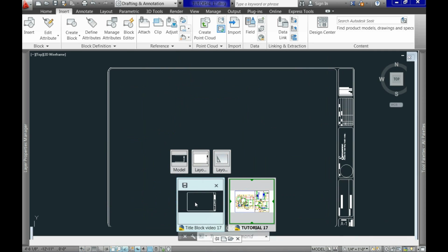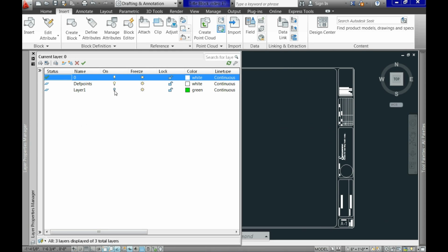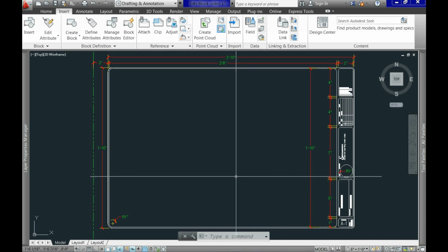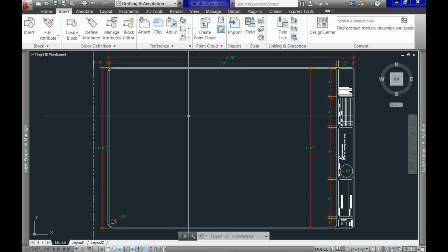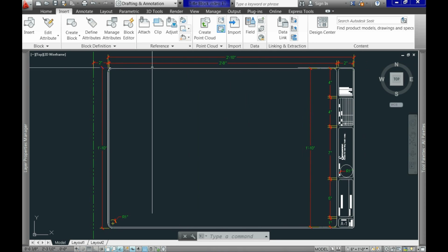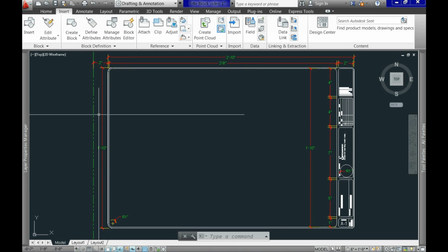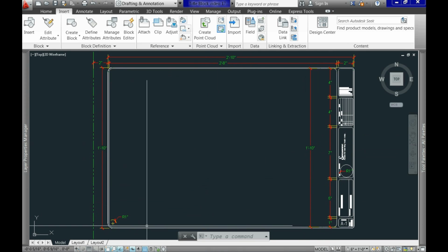Open a new drawing from our regular template and draw it line by line. Here on the screen, you have the one I'll be using, so you can stop the video and create it. If you wonder why it's not showing 36 inches by 24 inches, as is the size of our sheet of paper, of our paper space, just keep in mind we're leaving some space for the binding of multiple sheets once it's ready for plotting, and also for some type of comfort within the plotting process.